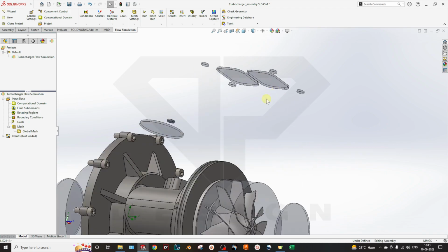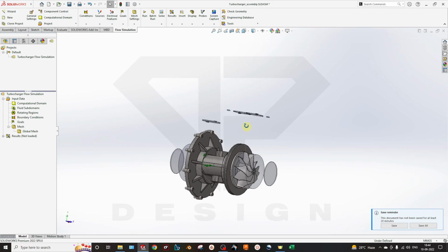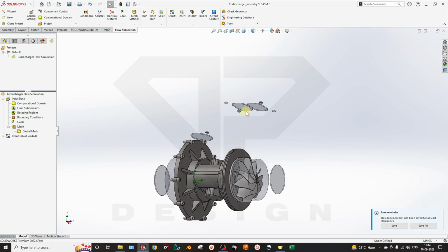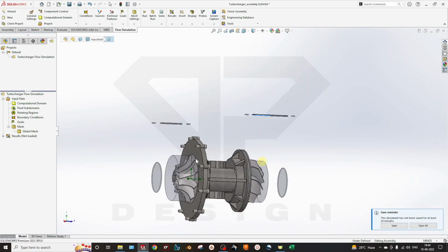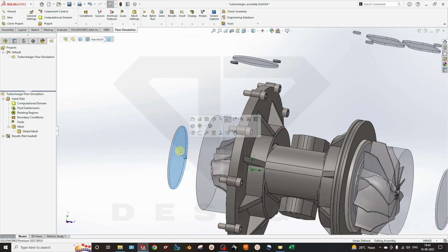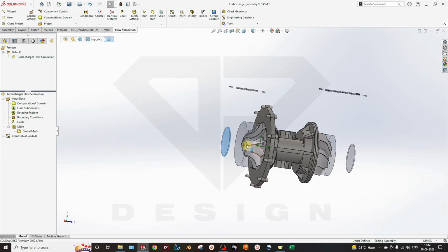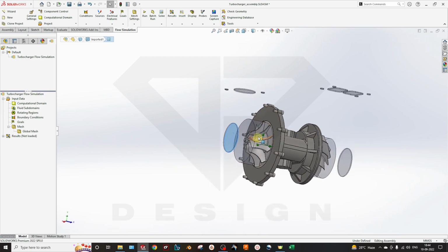And if you have done the mathematical calculation for the exhaust air outlet from the engine, you can input your inlet mass flow here. So I will assume 1 kg per second for this simulation, and here you can see your intake mass flow air, and this will go right here, and it will compress the air to the engine from this port.